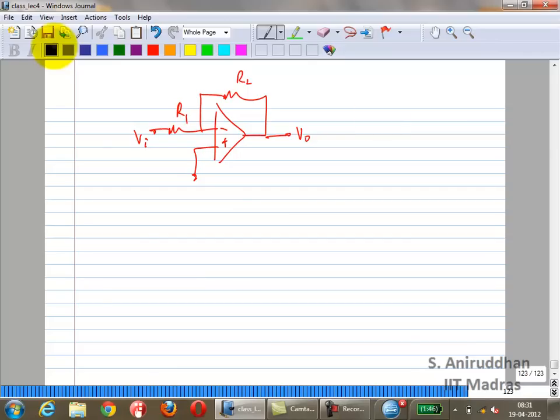So we have discussed this before. So let's say if one resistor is this, other resistor is this. You don't want to do this. You want to lay it out as maybe as two sections. You may do it this way. Okay. This will make sure, so these are your two resistors. Okay, you make sure they are the same orientation. What else?